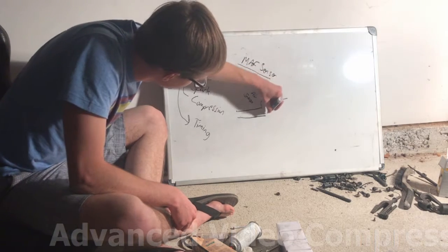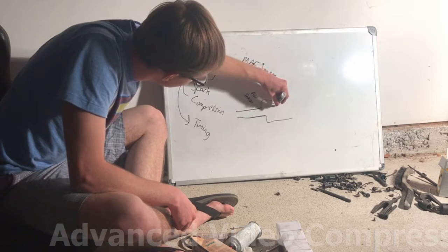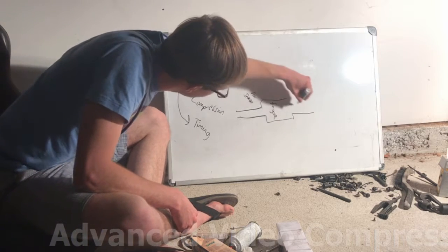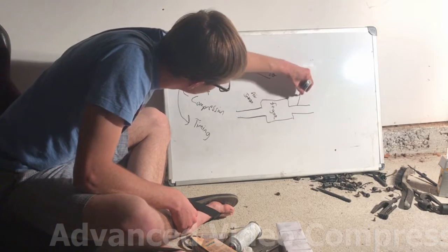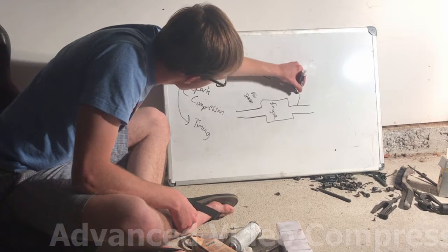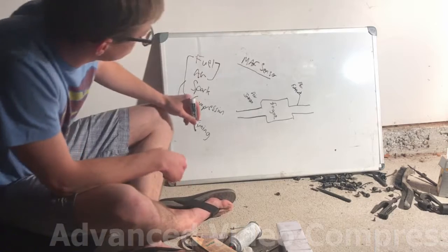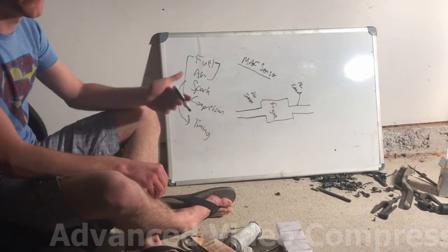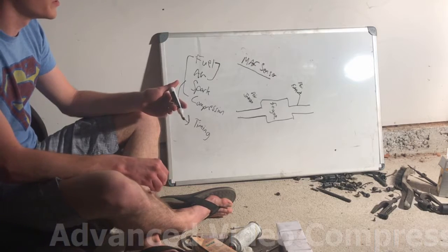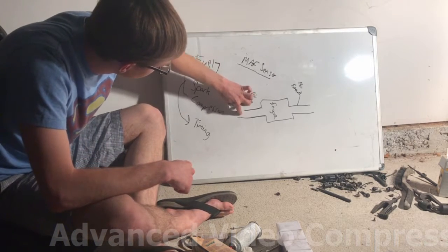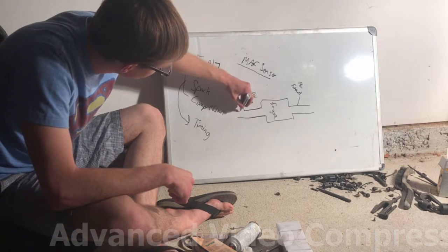This is our engine right here. And then we have air coming out of the engine. That's going to be our air exhaust. So looking at the air coming in, the job of the mass airflow sensor is to monitor the flow of the air coming into the engine. So that's generally going to be somewhere on your intake tube.